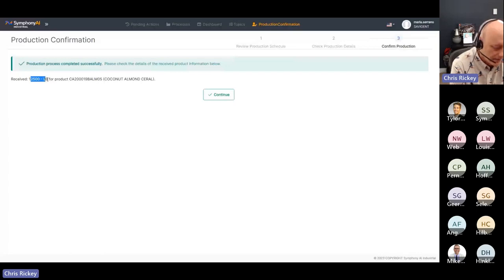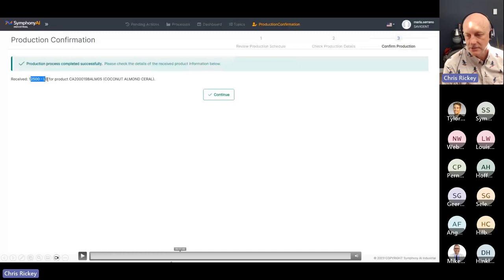The contract between the MES and the automation was the same, right? In both cases, we needed the order that was being produced against and the quantity of material that was produced. In both cases, the OPC was providing that data in one case and the MQTT message in the other. So the contract was the same, but the mechanism was different. That allows us to quickly and easily go into a new plant, put these workflows in place that make sense, and then just wire things up according to the local conditions. So let's move on.